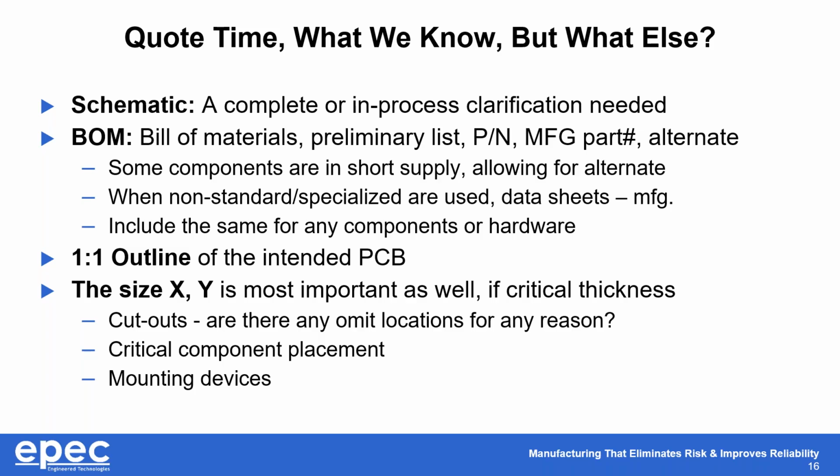Your outline, like I said, one-to-one with what your intention is for the area of usage. It doesn't have to be exact, but we need the overall X and Y distance, longest distance, both directions. Again, if you have any cutouts or critical component placements, if you can let us know those as well as mounting devices. So if you have some mounting holes that you need specifically met in those dimensions, or countersinks or counterbores, if you can let us know that at the time too, that'd be good.